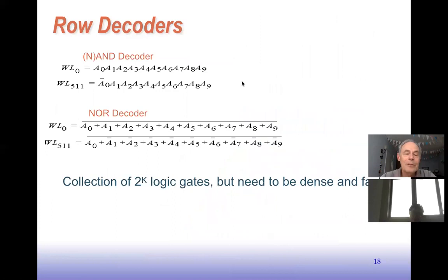Okay, so row decoder, what does a row decoder have to do? Well, it's like any other decoder. We've been talking about decoders all semester. And the only difference here is that typically they're big. There's lots of outputs, right? So here's an example in this slide, if we had 10 address bits, the output of the top row of the decoder would be the one that selects when the address is 0, and it would activate the 0 row. And then the bottom row would be the one that is activated when the address is the maximum.